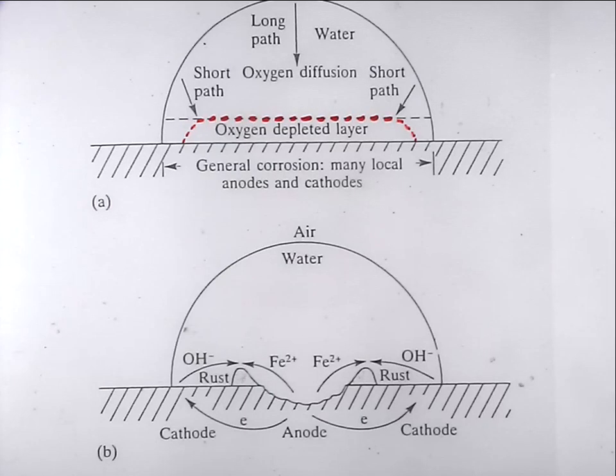Got another one here. This is stainless steel tubing from a chemical plant again. This tube, the failure is related to not draining the system down fully when it's not being used. And what there is in the tube is a brown stain, and that relates to the 6 o'clock position, the bottom of the tube.